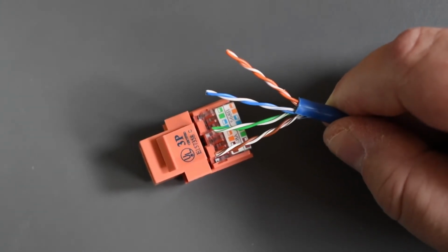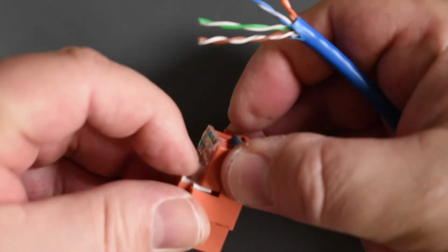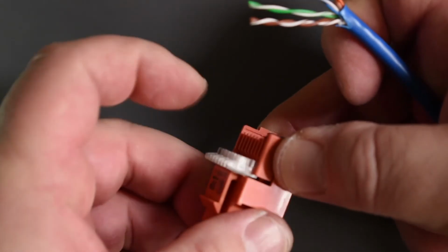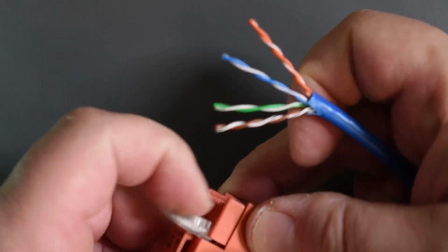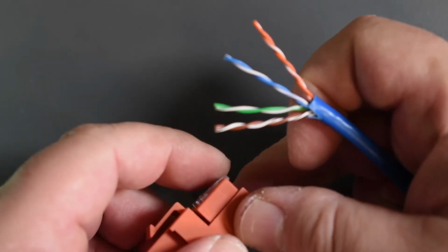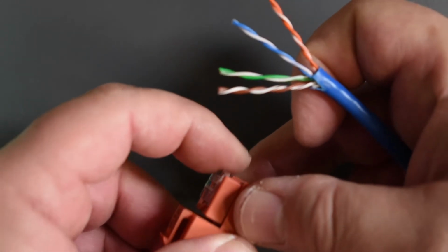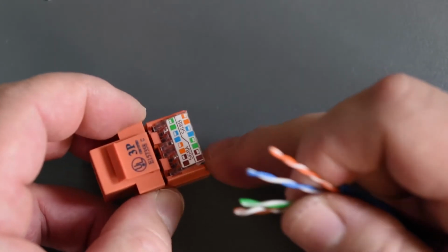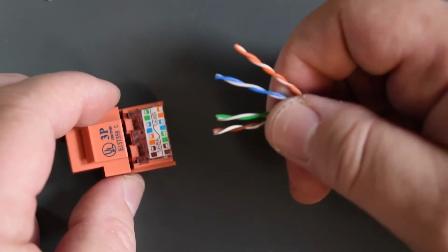I'm just going to do it a little bit quicker this time. Now we have removed that clip. Remember, here's that clip. Okay, so we'll take the clip off, put it somewhere that we don't lose it, and open the hinge. This one has been done a few times, so it opens quite easy. But if you have a brand new jack right off the bag, you're going to have a little bit of a harder time opening it. So don't worry, just open it. Okay. So here is brown, green, blue, and orange, and all the solids are on this side in this particular jack.